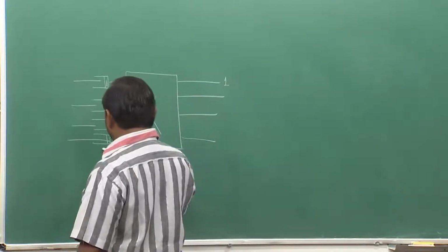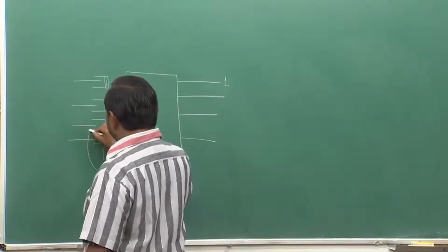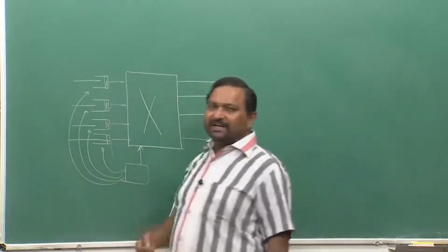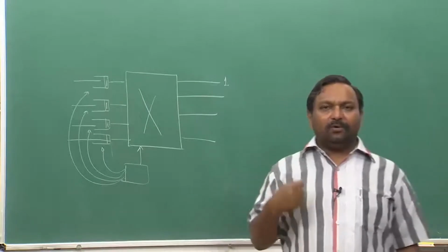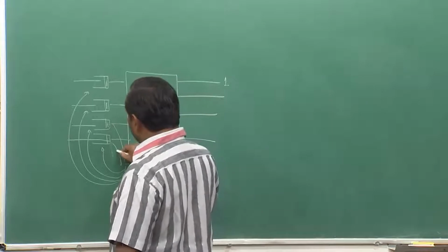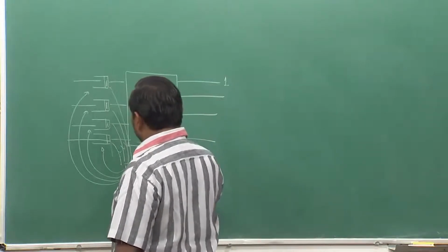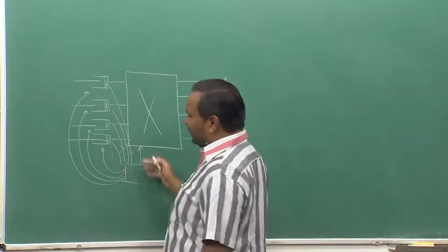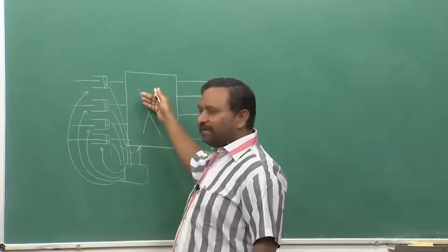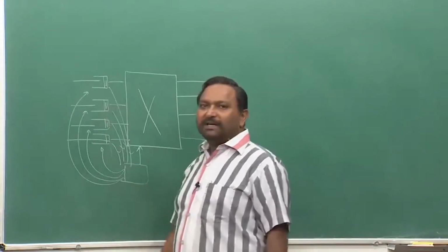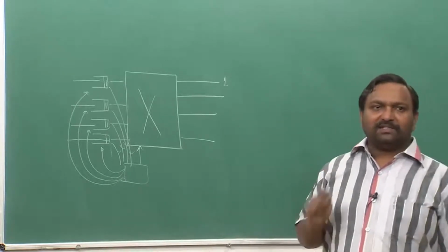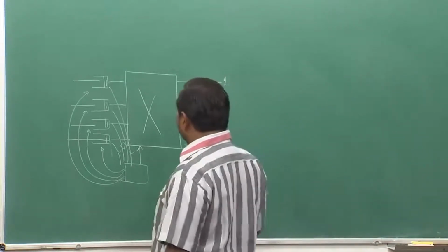So there is going to be a feedback which has to go to these interface boards also. They will essentially be throttled or regulated by the controller. As well as the switch being configured, the header information also needs to come back to the controller. So the controller has to do the computation, and based on that it will decide the next state of the switch, and it will give a command to the interface board whether a transmission should happen or not. Okay.